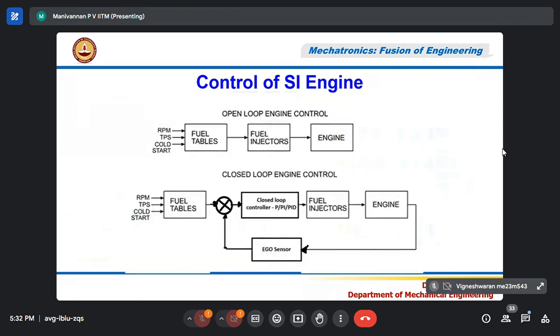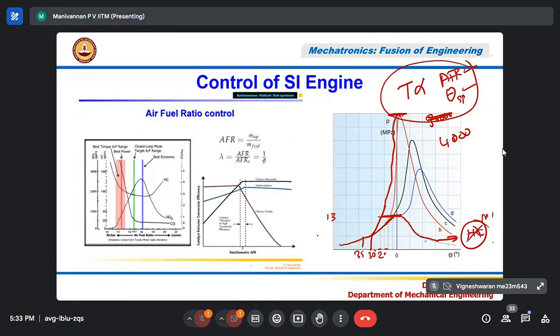I think you already explained this yesterday, but I was just thinking, what is the disadvantage of advancing the spark? If advancing the spark is always better for torque, then no. You have to give appropriate advance depending on engine speed. No disadvantage. If suppose you give wrong timing, that's what the ECU will do. If the spark timing is not sufficient, it will adjust the spark timing continuously, to see that maximum torque is supplied. That is its job. It will control air-fuel ratio and also the spark timing so that maximum torque is coming. That is the job of the ECU.